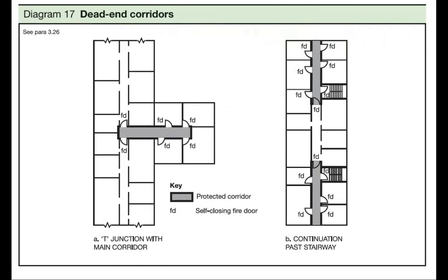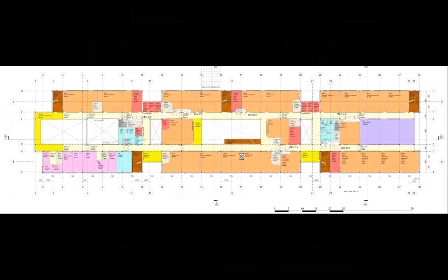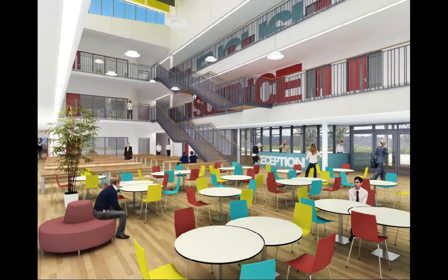The thing to bear in mind is that a plasterboard wall gives you 1 hour protection. So it's very easy to fire protect the corridor. As long as it's got the correct fire stopping, that gives you 1 hour. It's really easy to achieve, so you generally find most of your walls are giving you 1 hour's protection anyway. That was the example. That was the feature stair in that school. As you can see, it's open, which is why we discounted it.